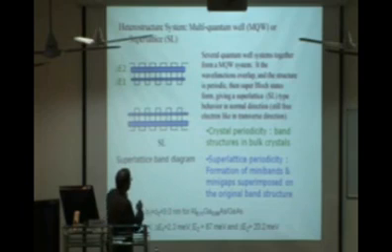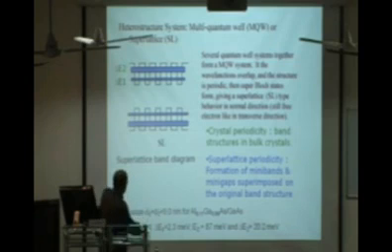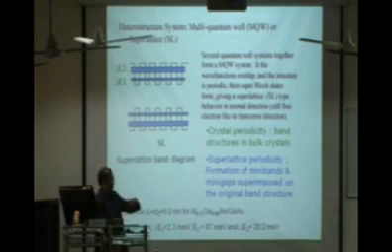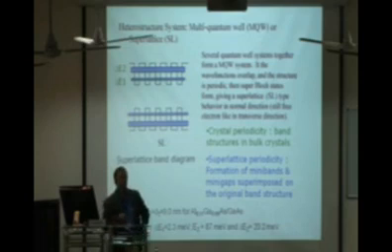In fact, these are very useful to get a unipolar laser. I talked about the terahertz also. Terahertz means very, very high frequency. So 1 terahertz is about 4 millielectron volt in terms of energy. So 60 millielectron volt means about 15 terahertz. So you can really get lasers or detectors out of this kind of superlattice structures which will operate in the very, very long wavelength radiation range, or the terahertz frequency range.